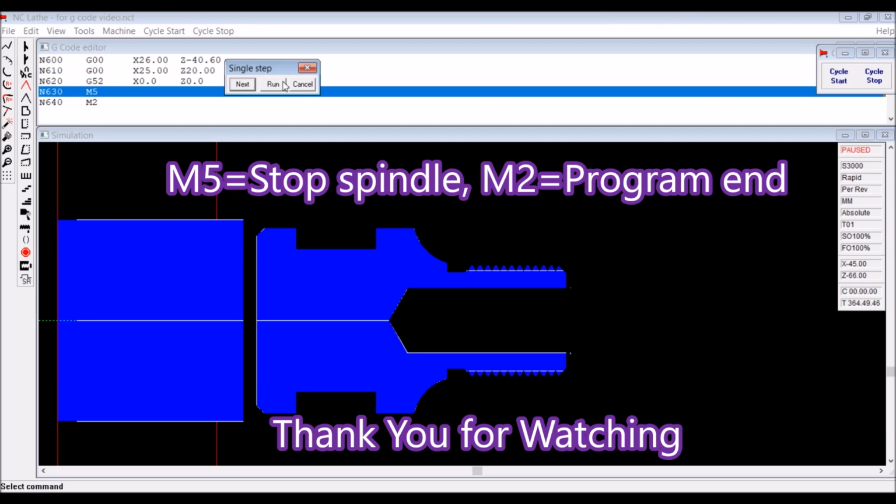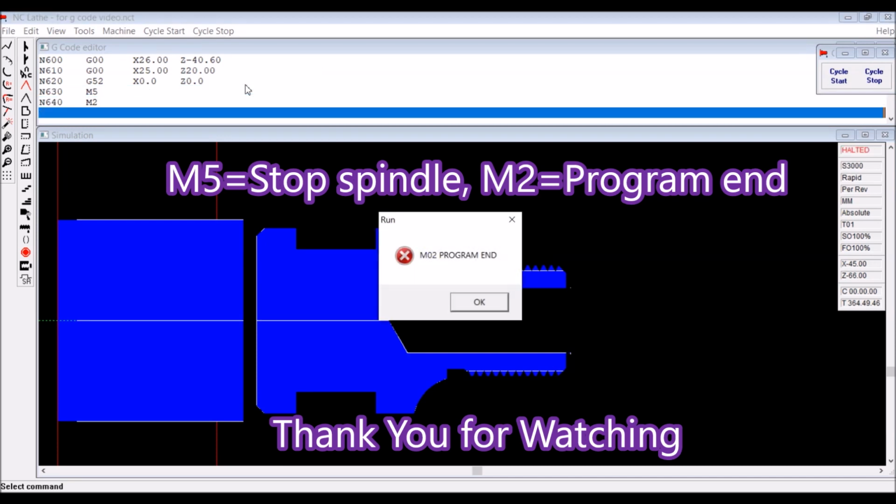So at the end then, when you terminate the program, M5 is stop spindle, M2 is the program end, and that's about it.